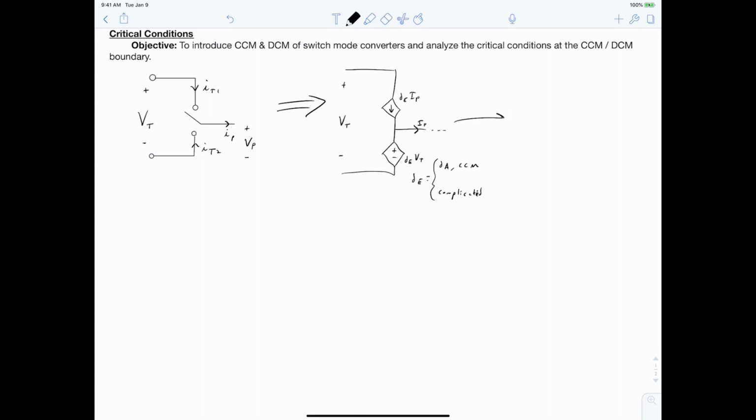And specifically, this case corresponded to a buck converter, where we can sketch the circuit on the left. And the duty ratio dA is the duty ratio of our active switch, whereas the duty ratio of the diode is considered to be dP, and dP is either equal to 1 minus dA for continuous conduction mode or some more complicated expression we had noted.